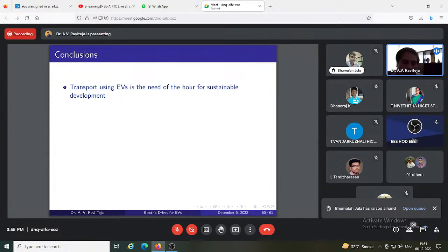And for induction motor drive, we have seen three control algorithms. Vector control gives the best performance, but it is complex. If you want importance only on performance, you can go for vector control. Whereas if you want to compromise a little on performance, but still have a less complex algorithm, then you can go for direct torque control or V/f control.